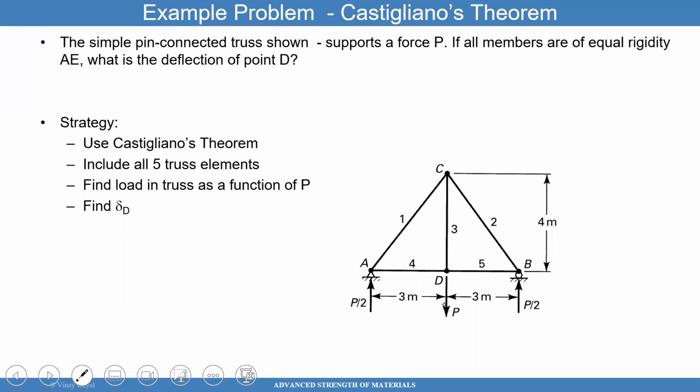Done. So what is the first step then in my process? Method of joints. So first do a free body diagram, and you find that this is P/2 and P/2. Then do a cut here, do a cut there, and you can slowly make your way through to find the forces. Exciting stuff. Okay, energy is exciting.